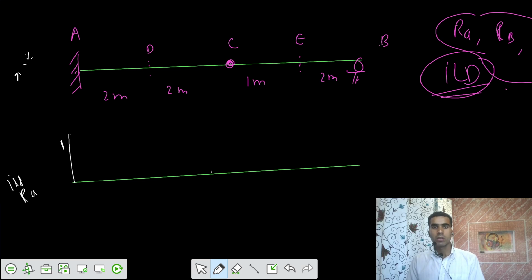After that, up to the point C, let's have that analysis here. So the hinge is C, this is C. This is support A, this is what you call a simple support B, and this is your fixed end A, C, B. The problem says to remove the restraint offered by the support A. Now you lift the entire thing by 1 unit.